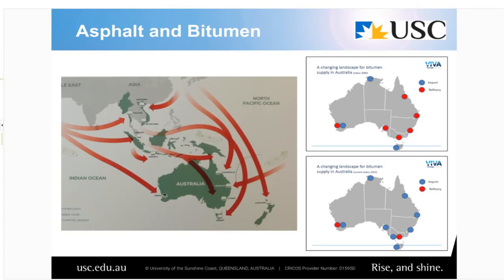So I think in the past we've been critical of imported bitumen, and I think it's less about the change in quality that's associated with imported product, but the variability and the fact that we now have to work harder to understand what we're getting and what we need to do to it to make it perform in the field, remembering there are no performance tests in our specification.